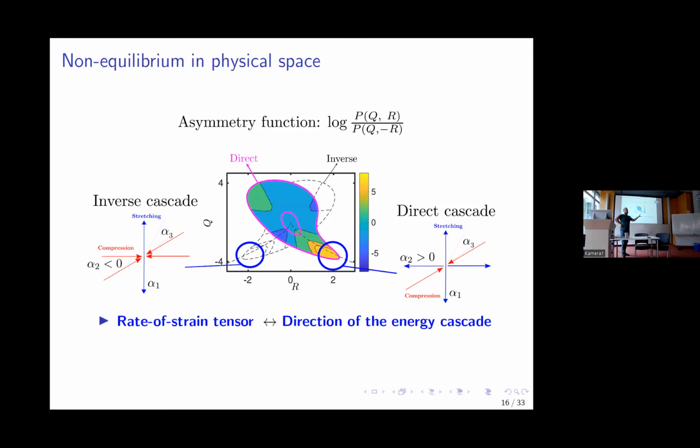If you take the rate of strain tensor and you average it over the full box, you get something that is isotropic, and it's true it doesn't have a direction. It's actually zero, but locally it matters. It matters to the equation. It matters to the way vorticity is generated and dissipated, or the way the strain is generated. Isotropic turbulence is statistically isotropic, but that doesn't mean that locally the flow is isotropic. Actually, the flow is highly anisotropic.